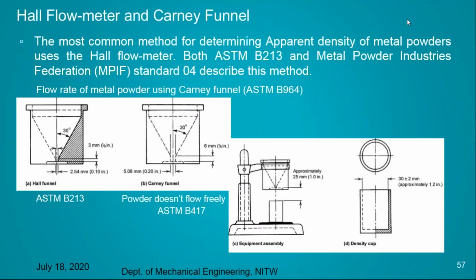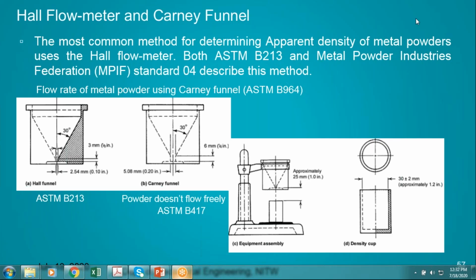And as I told you, the flowability can be measured in terms of the Hall flowmeter, especially for the additive manufacturing process. ASTM F3049 is meant for analyzing the flowability properties of the powder, especially for additive manufacturing. That standard was developed with the National Institute of Standards from the USA and the ASTM F42 committee, and they developed ASTM F3049 for analyzing powder particles for additive manufacturing. These are all the existing methods we use for powder metallurgy, for metal injection molding, or for additive manufacturing powder analysis.